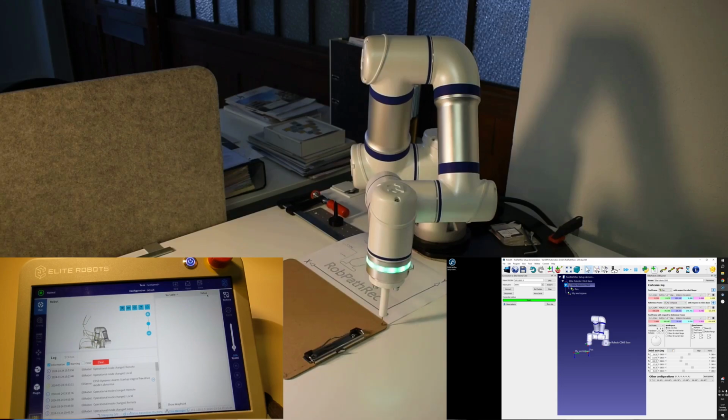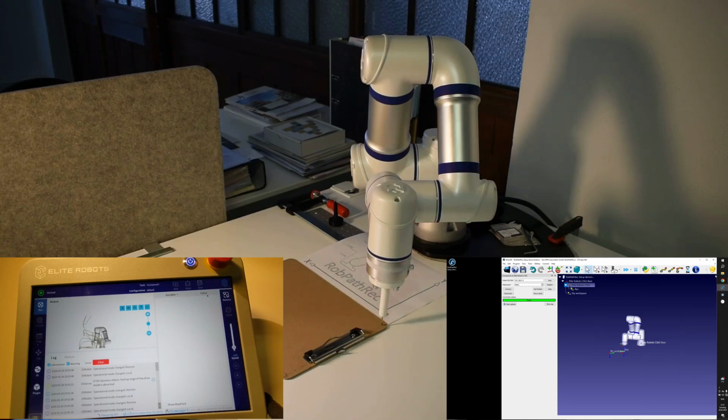Okay, as a last one, before we can start with the first recording, we should define a home position. The home position is necessary because for many cobots, the configuration might be a little bit strange with regard to the home position, and we want to make sure that the very first position you go to is always a predefined position, so you can reach all other steps later on in a correct way.